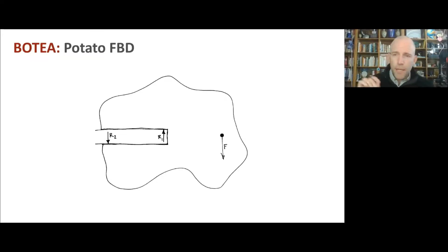But if we do a little bit of maybe just sort of order of magnitude analysis here, we're going to see that the contribution of the friction force is going to be kind of small compared to the contribution of these reaction forces, at least with the kind of geometry we've got here. So one thing to keep in mind is that the friction force, if we're not moving, would be at most mu Fn, right?